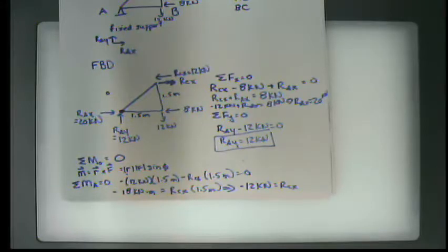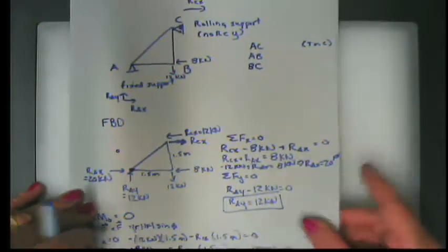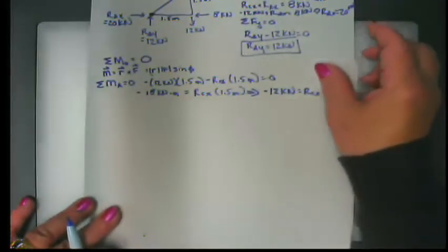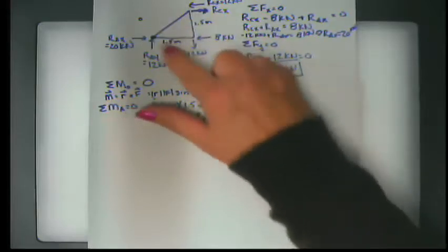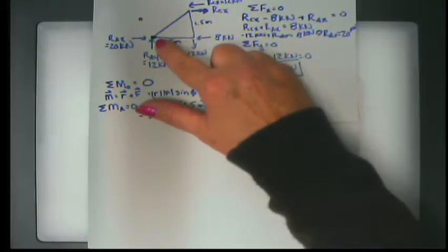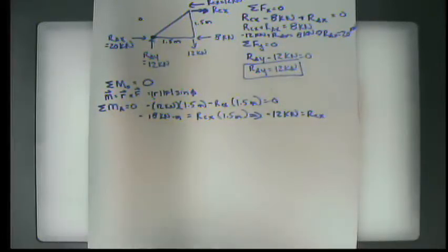Okay. All right, so let's continue our work. Now we know what the truss looks like. Now we're ready to dig into the method of joints. Now, the one thing that you need to know about the method of joints is that you only have two equations of equilibrium. You only have summation of forces in x and summation of forces in y. After you get done with the free body analysis, there's no moment equation because everything's going through point A, so all the moments are 0.